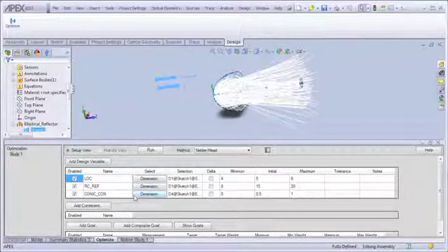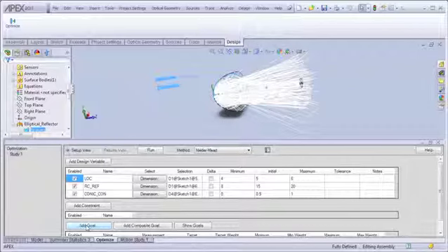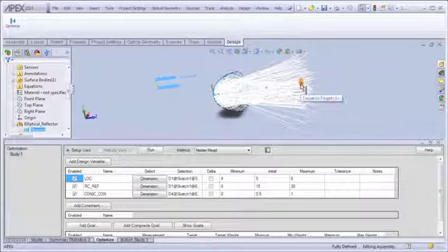Setting up an optimization study in Apex involves these essential activities: defining variables that can modify the specified geometry, setting any desired constraints, which create direct or indirect relationships among the design variables and possibly the merit function used to limit or restrict the variable range, defining goals, which are some type of performance target you wish to achieve, and then selecting the surface measurement to which a goal is applied, running the automated optimization process, and then viewing the results on the Active Study tab.